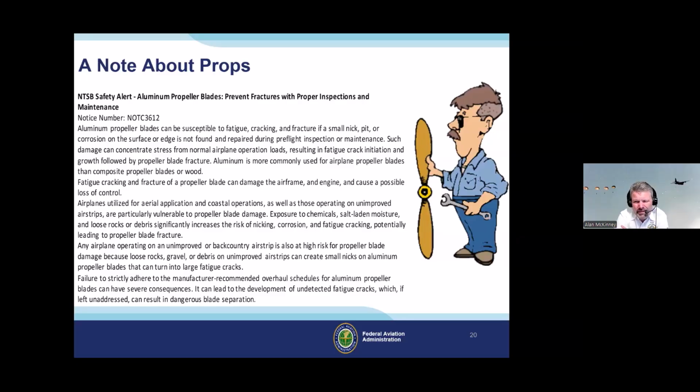And remember, it's dynamic, so it's supposed to be balanced. So if you take material off of one side, to make it continue to be balanced, you would have to take the same amount off the other, or you would have to add what you just took off to the side you just took it off of, or you'd have to balance it and then figure out where, on the spinner bulkhead or whatever, to balance it.